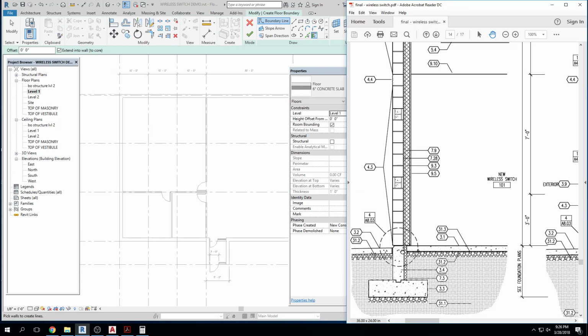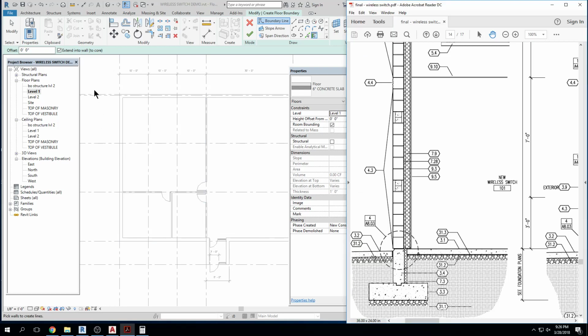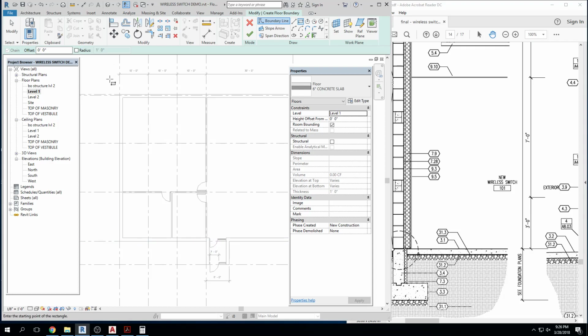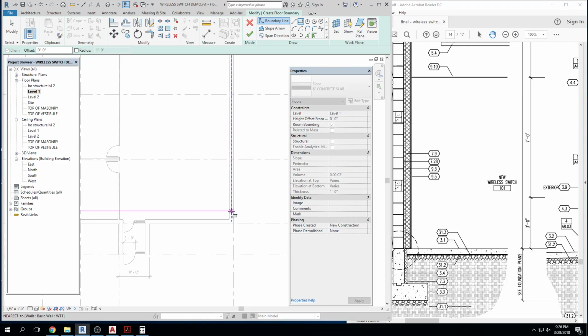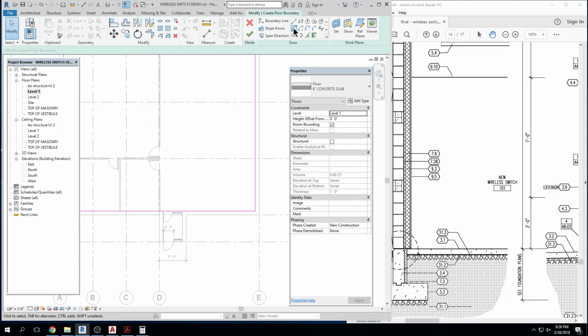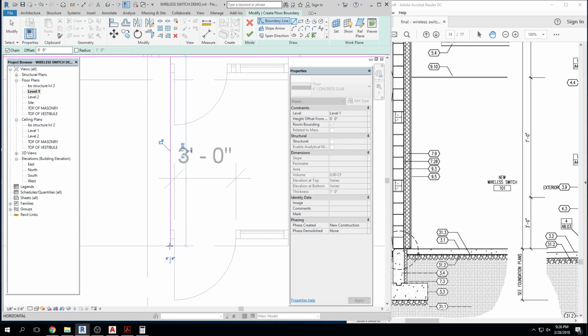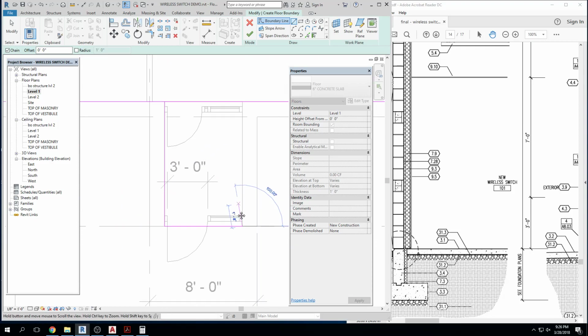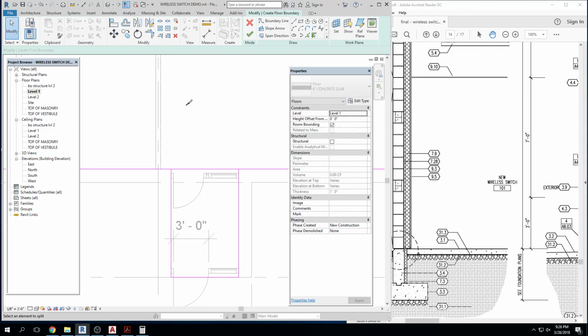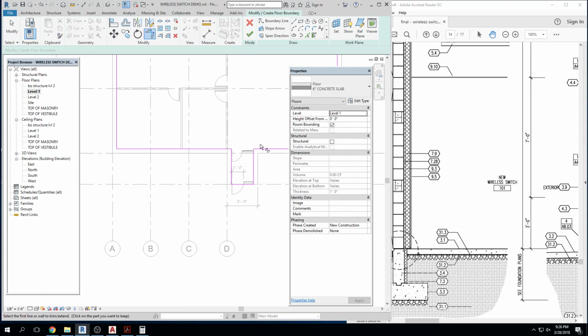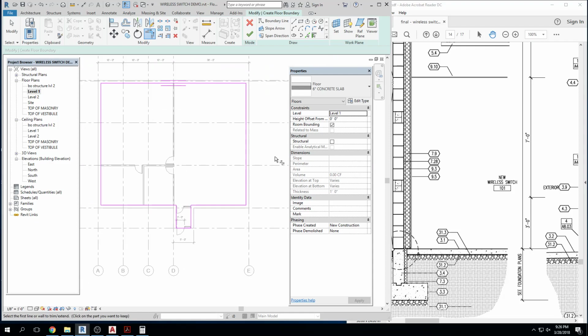And I'm just going to bring it up against the wall. I'm not going to stop it for the insulation. We'll just call it good. So this is basically a big rectangle, although I have to draw this down here, but really it's a big rectangle. So click, click. And then I just draw my little extension here. Ooh, that's bad. Right. Split, SL, click, escape, trim, TR, click, click, click, click. Right, and I've got the outline of my floor. It's resting at level 1. I'm going to hit finish.